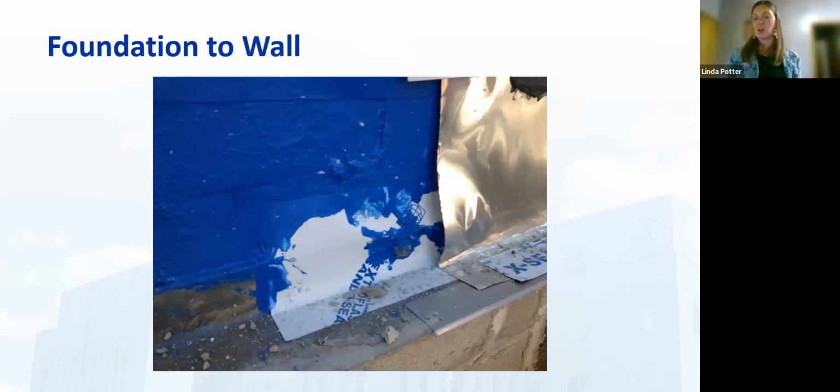Same thing for foundation to wall. Spell out how we want that to look. I've seen some really nasty things end up happening out there. We want that air barrier to come all the way down before the rest of these components go on top, because it's like a present. So how are we managing that below-foundation into that above-grade wall assembly? How are we bringing those two together to meet?